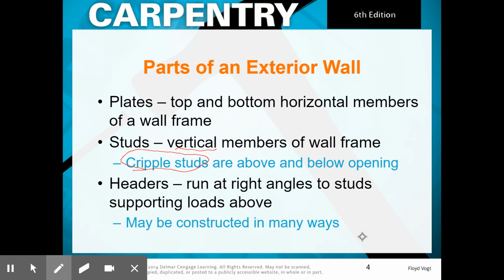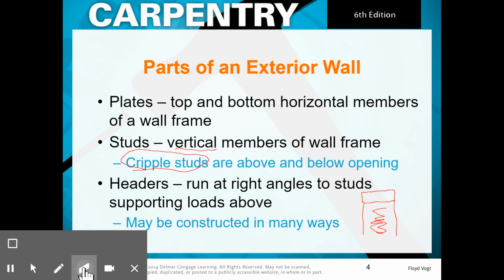Because we're creating a cavity in the wall, right, we're taking out the studs that could be in the center here, so this is just an opening. By putting the header up, we help bridge that and strengthen this opening. And the headers can be built in a variety of ways.